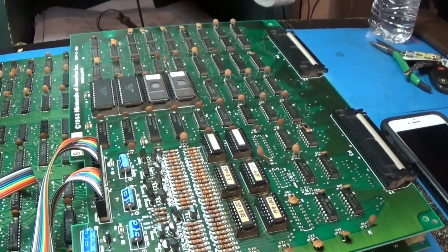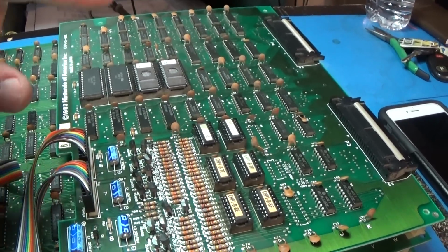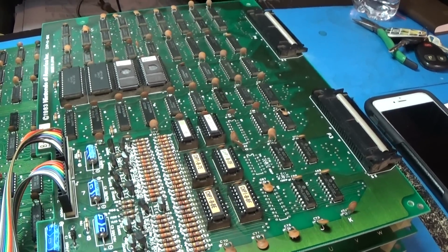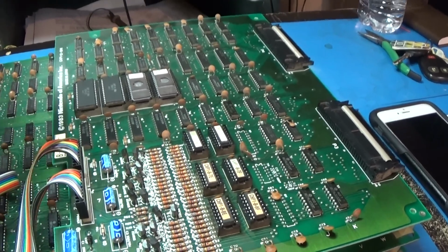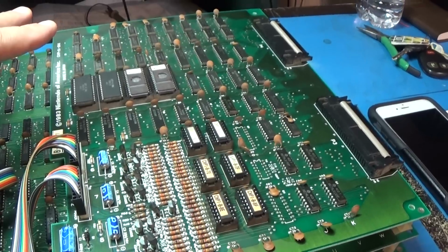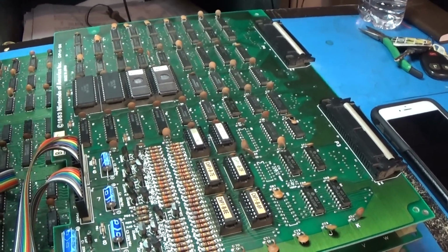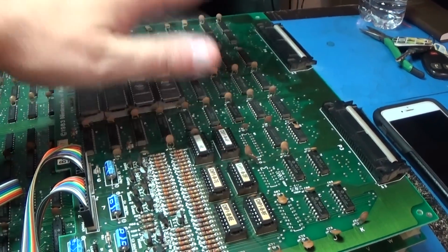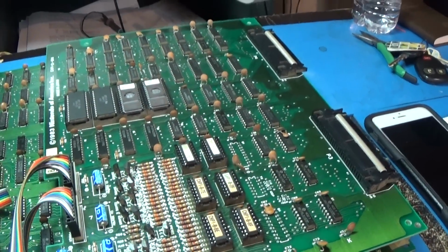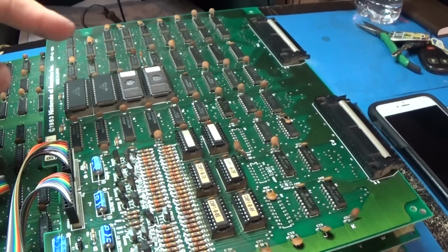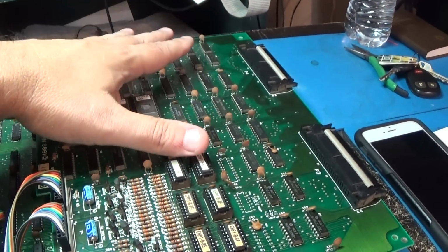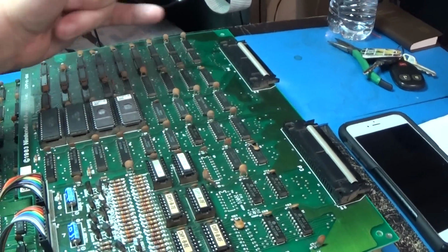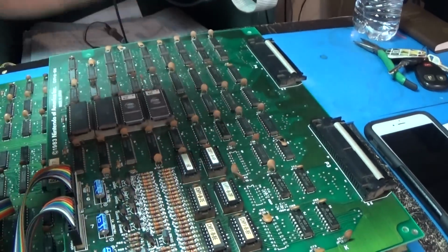Okay, I was doing a little thinking, looking at the schematic with this back PCB. I know that when I had my Fluke hooked up to this, I could read and write, do RAM checks on the RAM that's back here on the back PCB, no problem. So the problem is not in the write side. The problem is the read side of these RAMs, the hardware reading the data out of these RAMs and pumping it to where it needs to go.